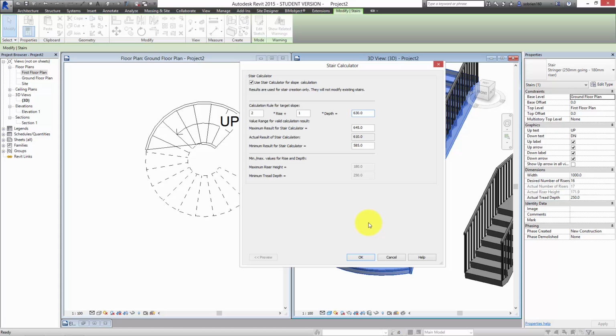In the UK and Ireland, the stairs are very, very low in private houses because they have to be made for people that are ambulant disabled, people who have problems with sight, elderly people that have to stop halfway up the stairs. They're very, very low. In Northern Europe, the rules are much, much more relaxed. They don't have those specific rules regarding lifetime housing and ambulant disabled, so you can get away with steeper stairs.